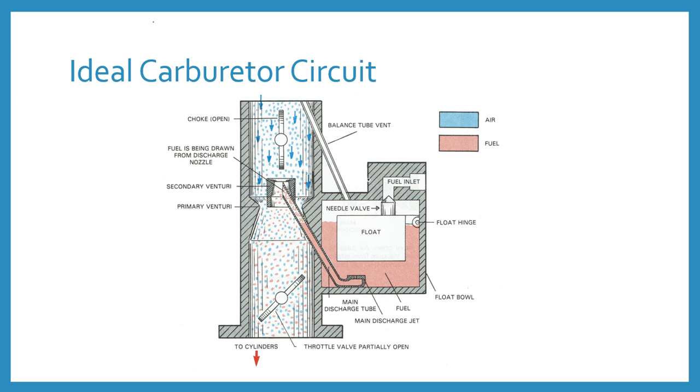The tip of the screw is tapered so that the air and fuel mixture is reduced when the screw is turned clockwise. Each screw can be set to suit the individual engine. The idle mixture adjusting screw is set at the factory itself, and some carburetors have a tamper-proof cap on the screw to prevent changes to the setting.